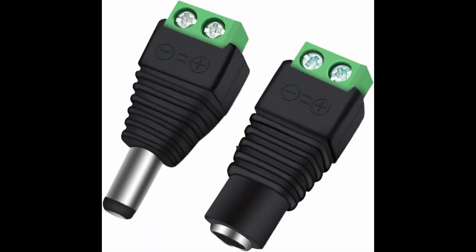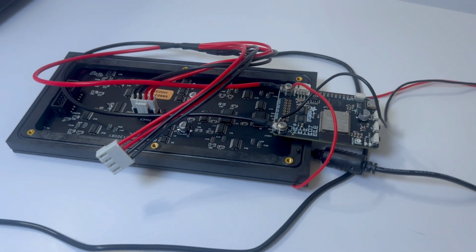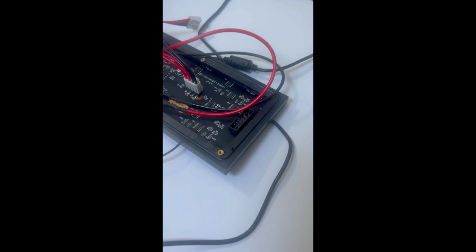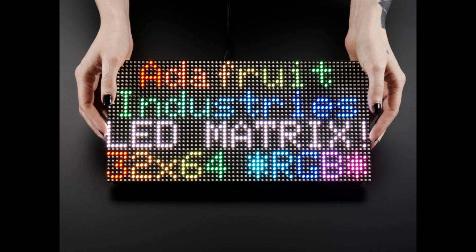One nice thing about this project is how simple the wiring is. The Matrix Portal slides directly into the connector on the back of the LED matrix. No soldering required. You may notice the connector on the Matrix Portal has more pins than the matrix. That's normal. The portal supports multiple matrix types, so not all pins are used in every setup.